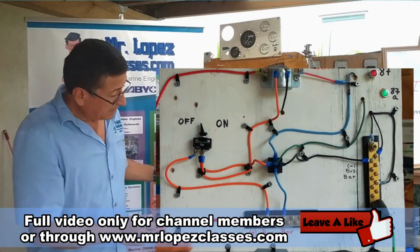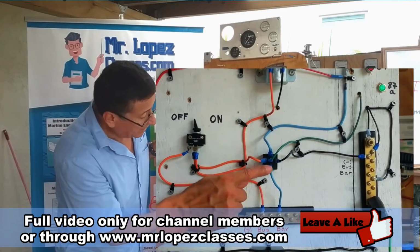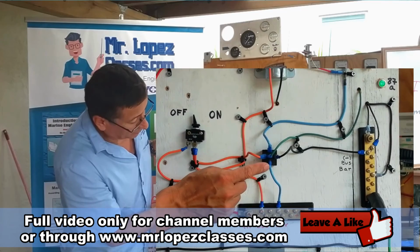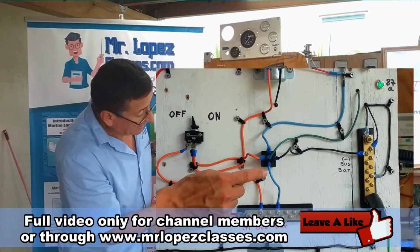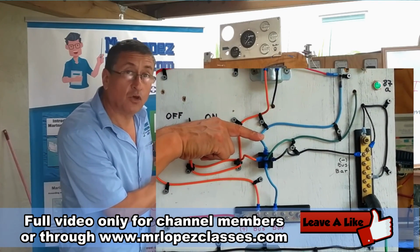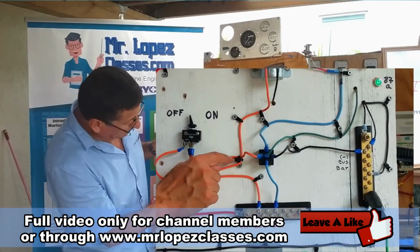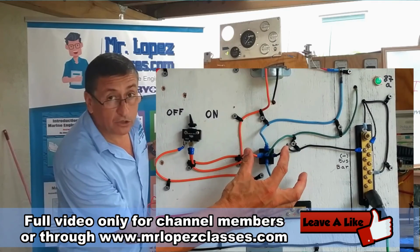In this board, the input signal, the signal in terminal 30, is coming from this positive common bus bar. And we have two signals, one in the middle. The connection between 30 and 87A in the middle is normally closed. And the connection between 30 and 87 outside is normally open. At this moment, this is the switch for the power in the coil, this is the negative, and this is the positive. At this moment the switch is off. No power on the coil.